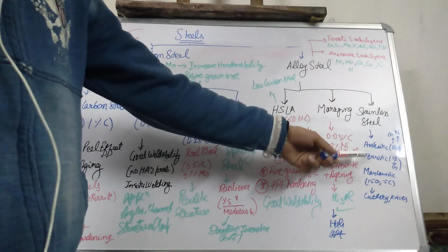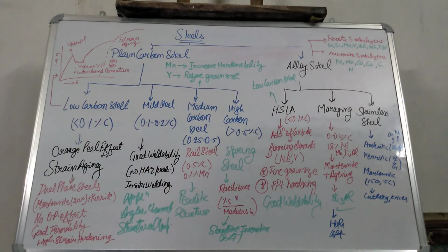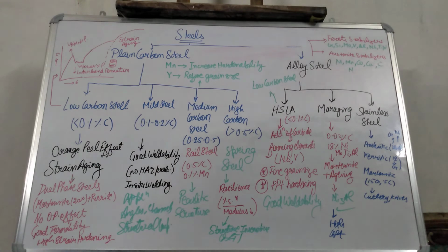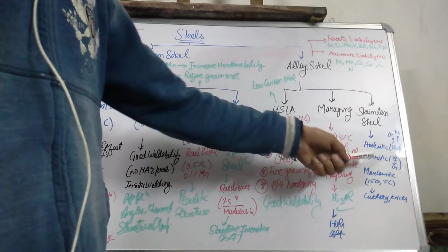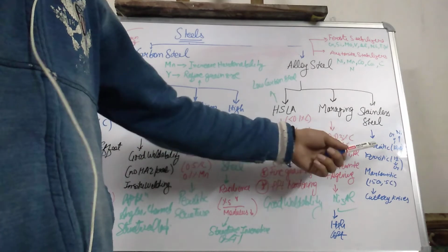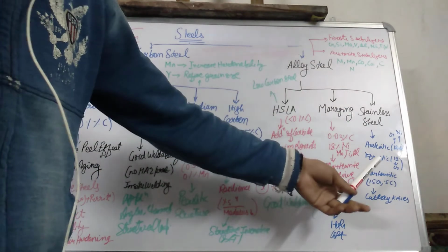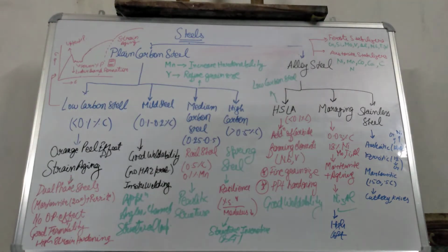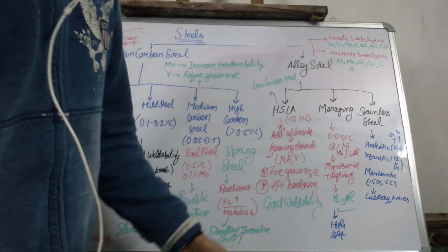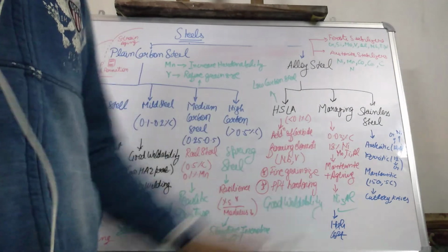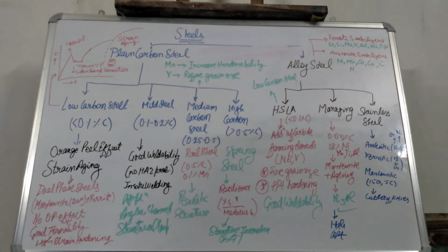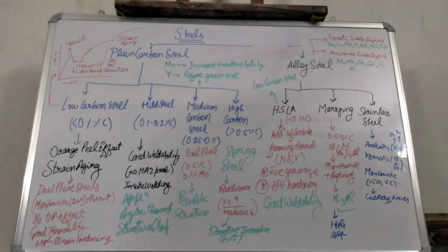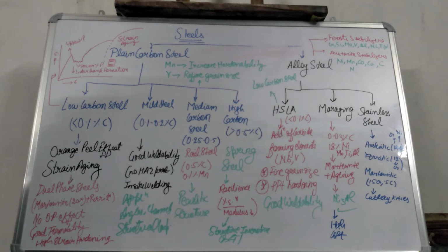Another category is martensitic stainless steels. In the ferritic stainless steels we have a very small portion of carbon, so the austenitic phase field is almost eliminated. But if the carbon content is increased without addition of an austenite stabilizer, we still get an austenitic field, and upon quenching from the austenite we have martensite formation. They have much higher strength than the ferritic stainless steel, so they are used in applications where hardness is a desirable property, such as knives and cutlery and other sharp edge materials.